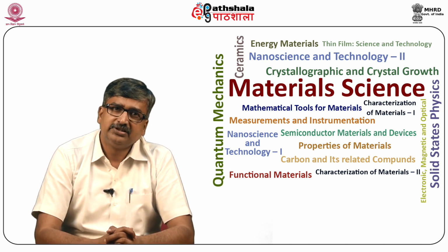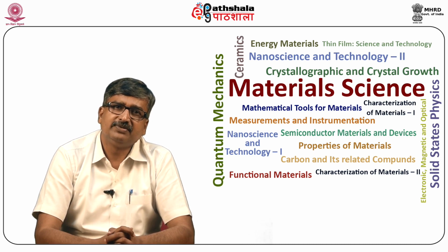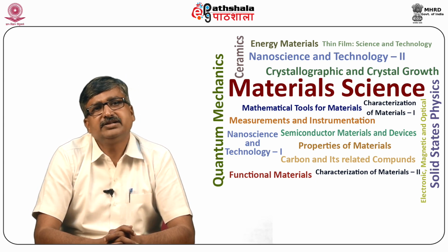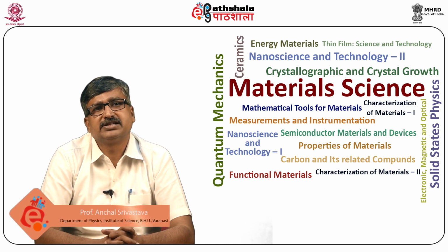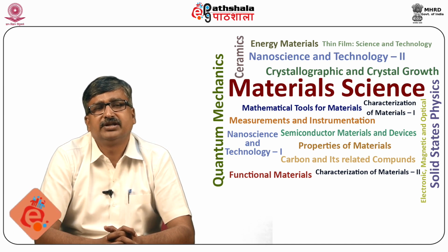So student, let us now summarize what we have learned in this module. We have learned the basics of the electrospinning setup. We have also learned the formation of polymer nanofibers under high voltage in the electrospinning technique, formation of the Taylor cone under high voltage, charging of polymers, jet formation and flight thinning, and requirements of different controlling parameters such as solution and processing parameters for good quality growth of nanofibers.